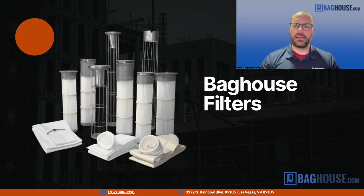So the polyester bags are good up to about 265 degrees Fahrenheit. As long as we're under that temperature, we're pretty much going to use polyester bags exclusively, because they're the cheapest, the most robust, and the most widely used, and least reactive. If the temperature exceeds that, then we're probably going to go to aramid next, which also is very robust. And then in certain cases, if the temperature is above 400, which is about the limit of most aramid medias,